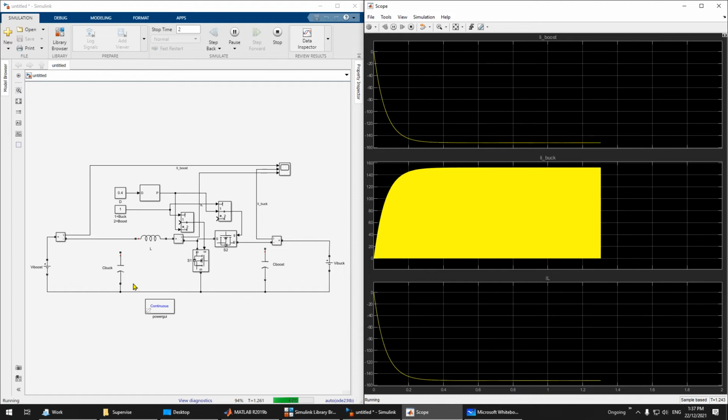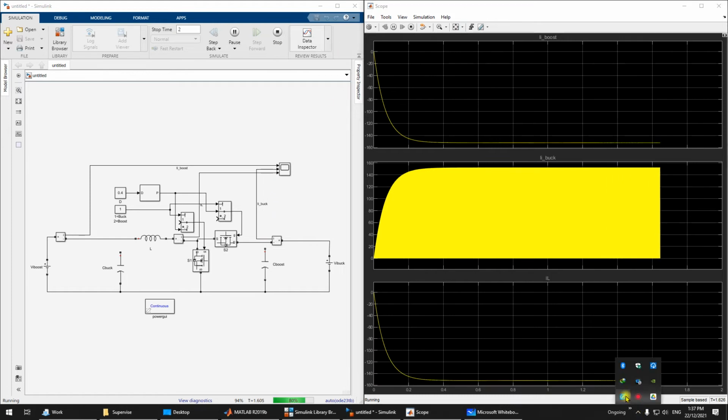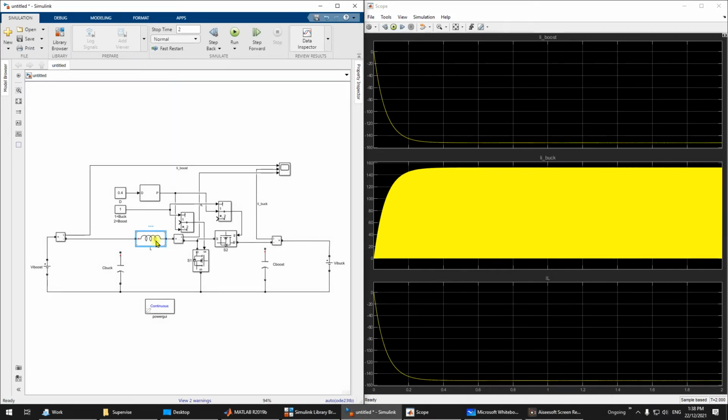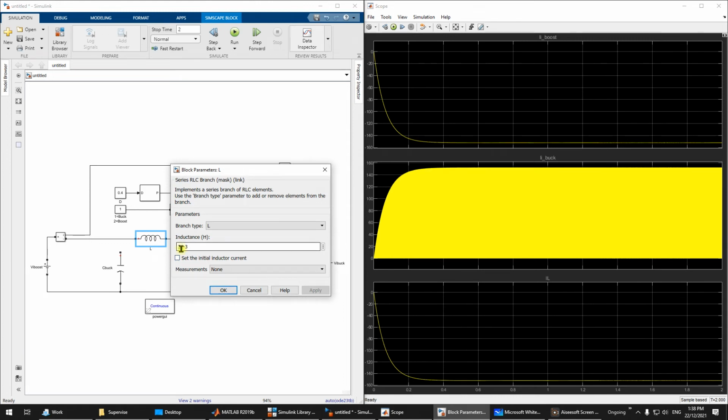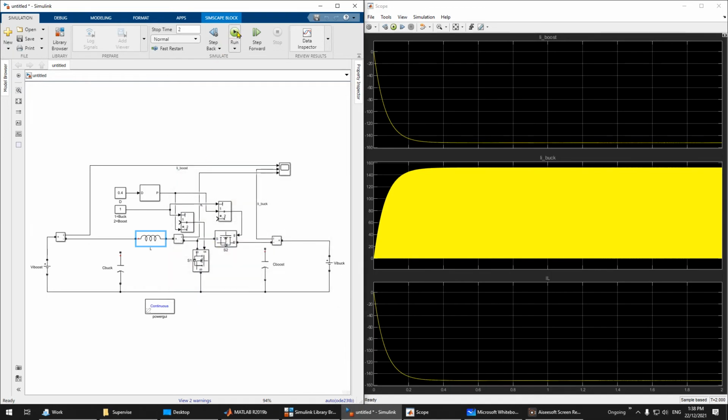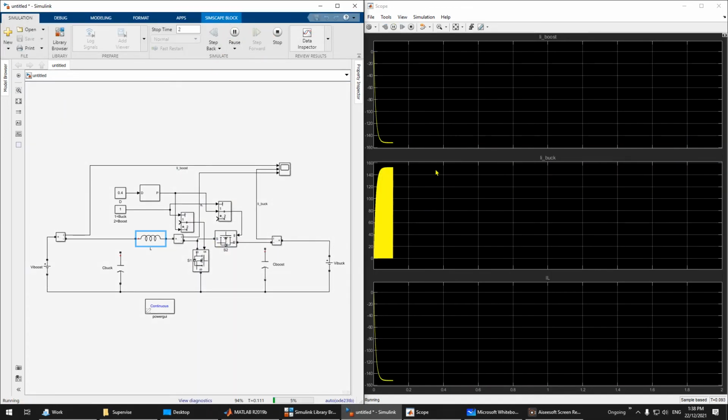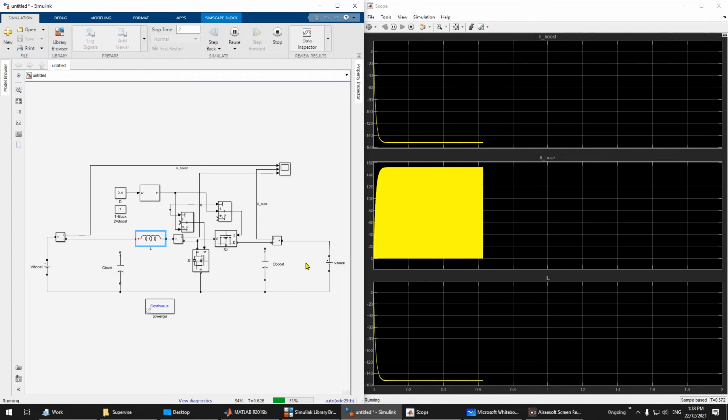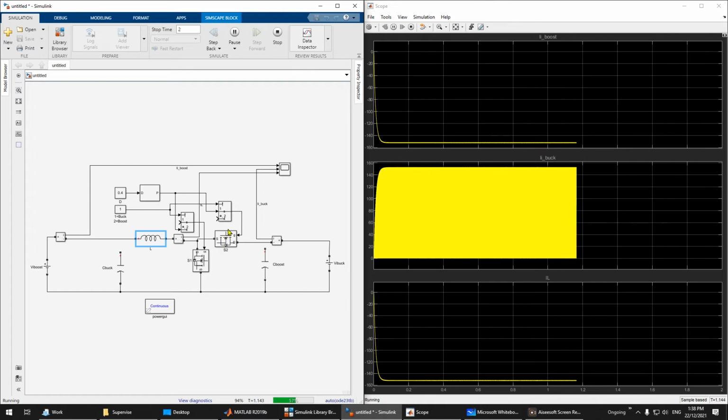So maybe I should check the recording first. Okay, for this case it's okay, but if the inductor is quite small, maybe 0.5, this effect might be severe. So still not severe. You can see here the ripple is quite large because of the switching effect of the S2.